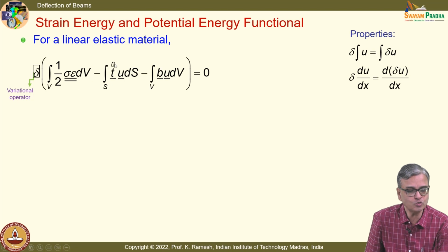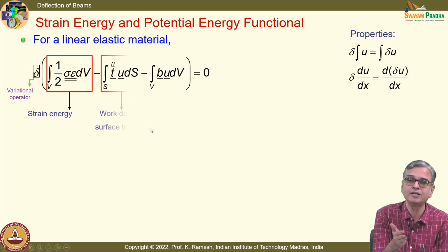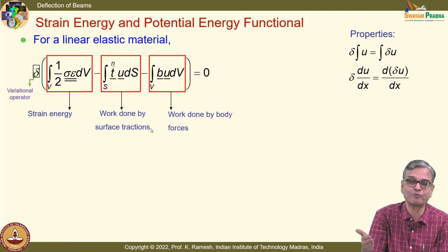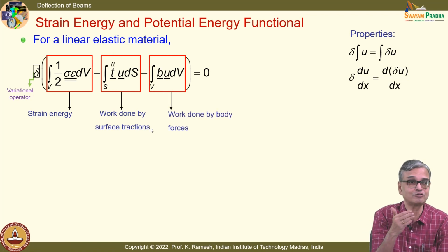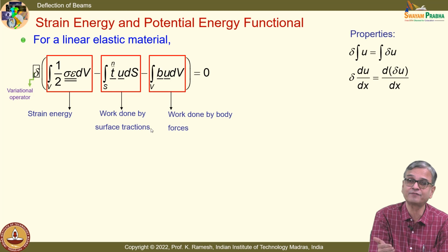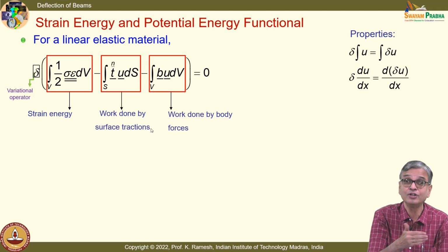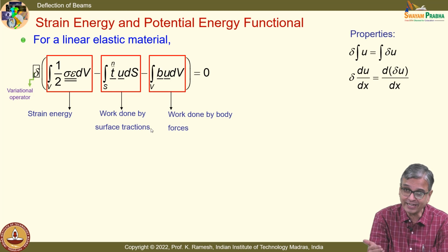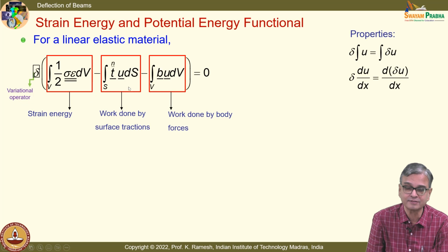This is how it is an operator. And they also use a different symbolism. This is nothing but your stress vector. Instead of putting it as capital T, they put it as a small t. And you know from Cauchy's formula how to find out the traction on the boundary. I have also said the discussion on free surface is very, very important, so that you are in a position to write the traction correctly. Even in a finite element course, you have to do this.